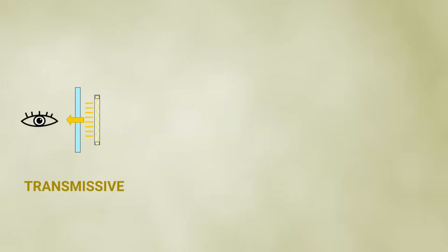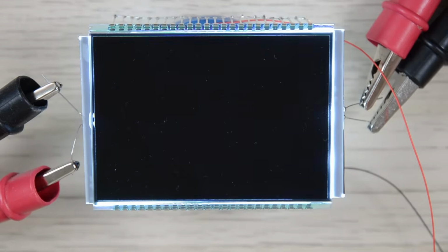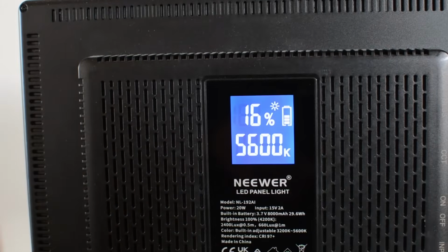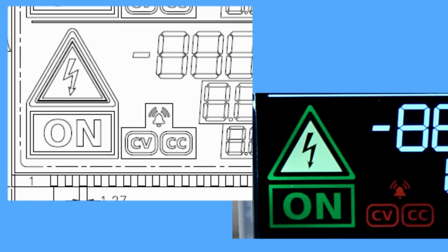Transmissive LCDs rely on a backlight, which allows for light segments on a dark background. For example, the background can be black or deep blue, and the segments can be any light color you want, as the color is printed on a transparent film acting as a filter. Transflective LCDs combine both effects, making them usable in a wide range of lighting conditions.